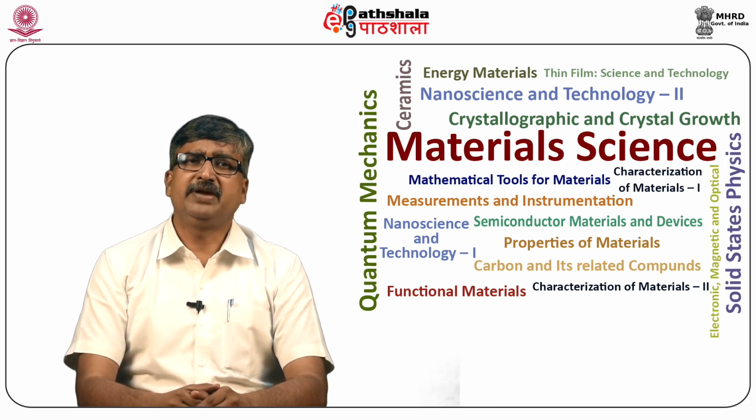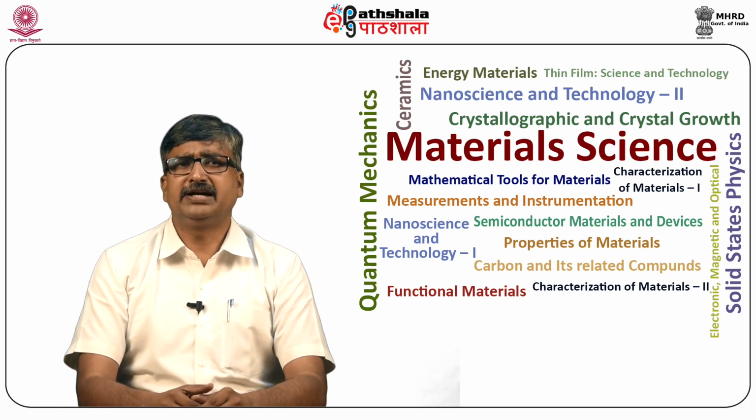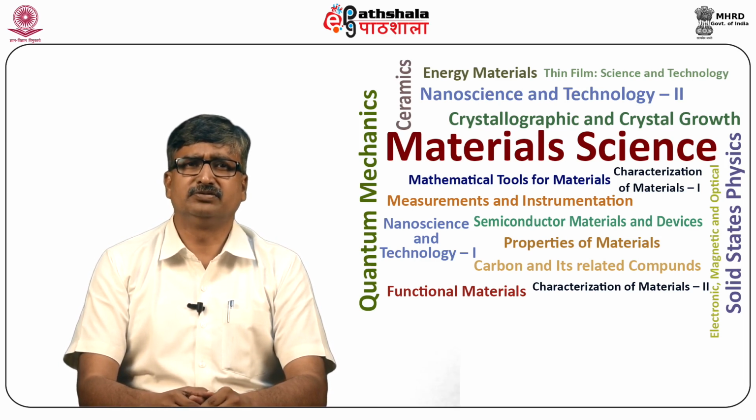The first one is the spray pyrolysis technique, where a mixture solution of benzene and ferrocene has been used for the synthesis of CNT. We optimized the conditions of flow time, the concentration of ferrocene in benzene, and many other parameters, which give good growth of aligned carbon nanotubes. The effect of argon gas flow rate and the concentration are important parameters and have been discussed for the growth of CNT in this module.